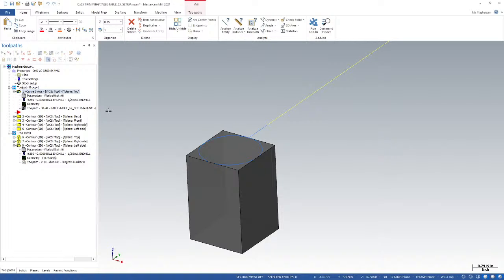So by default, the post processor, at least the older generic Fanuc 5X mill post, was set up so that you made your configuration changes inside the post processor itself, and you weren't changing output in Mastercam by adjusting the machine definition. Now, CNC Software has developed some new posts that do have that capability, but that's kind of beyond the scope of what we're talking about today.